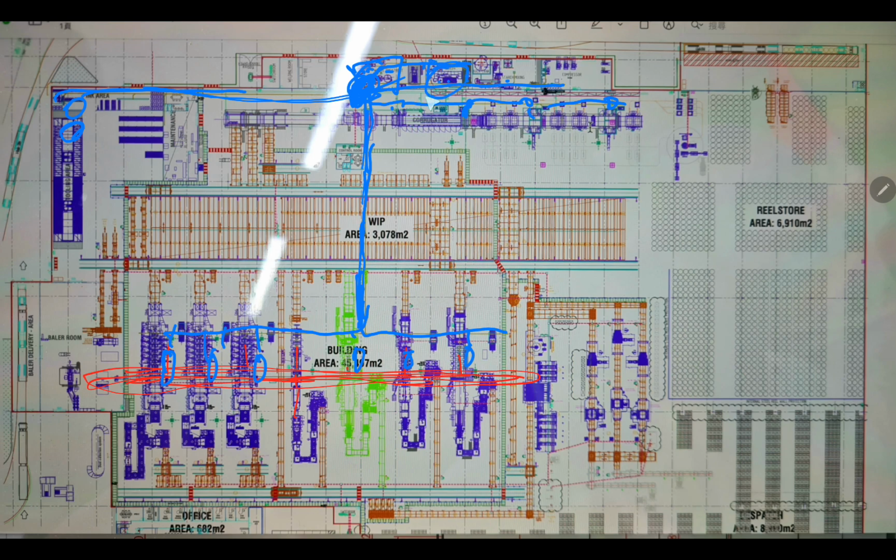You should try to install the effluent plant as per the water quality. What is the water quality in which place? The sea level, the water quality, and if possible you install the RO plant with auto dosing to save your boiler. The boiler is not a machine. I think the boiler is a bomb that we are installing in the factory. So do not take it lightly.